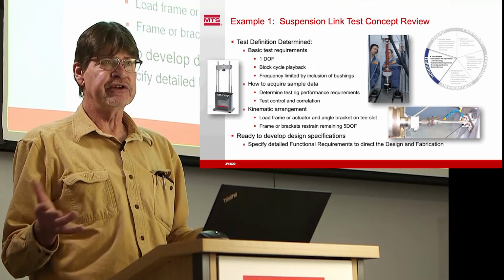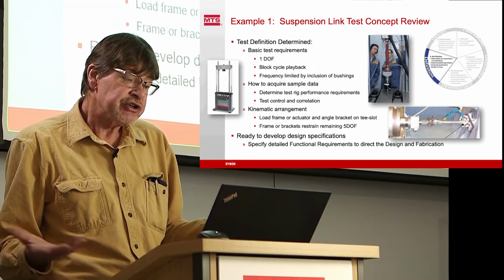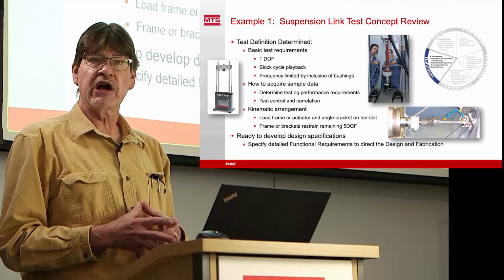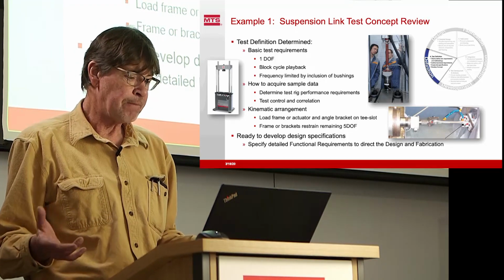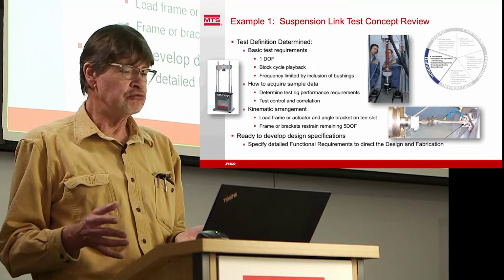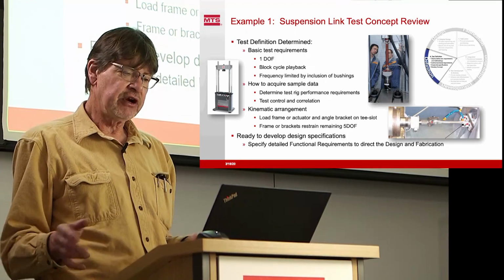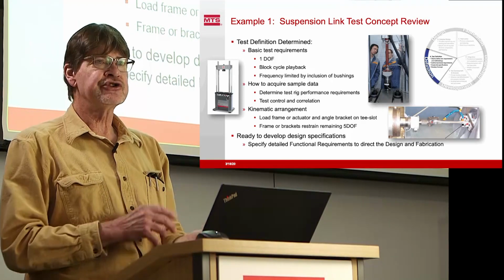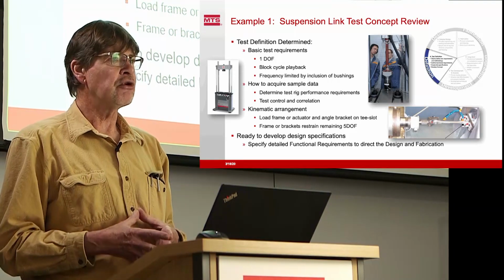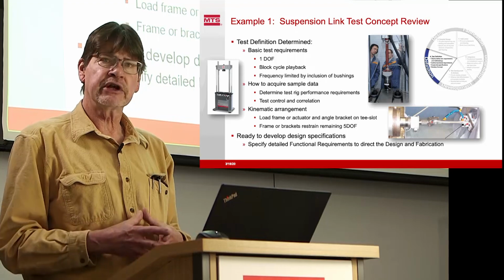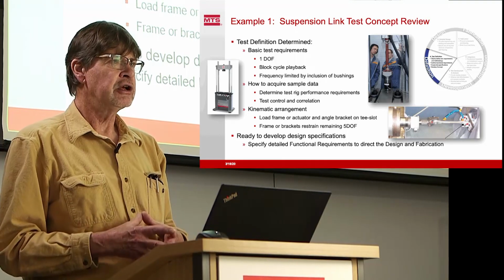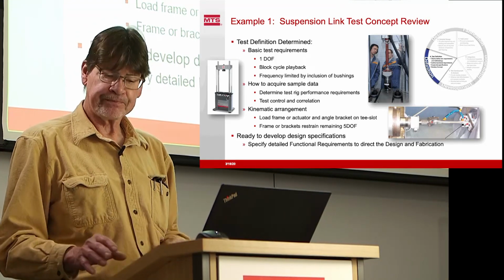Kinematic arrangements are going to be easy. Tension compression is fine. You know, that's a load frame job, or like I say, brackets on a T-slot plate. So based on this quick review, we can write our design functional requirements right from here. We need a bracket, we need this load, we need this stroke, we need this control capability. Boom, we can start designing. We can work right directly with the technician and come right to this test.